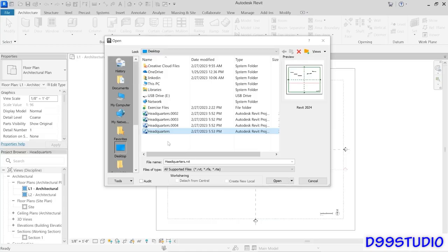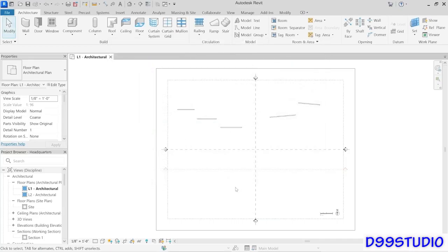So if you get in the habit of saving often, not only are you keeping your file up to date and potentially avoiding the annoying save reminder dialog, but you are also getting several backup copies that you can fall back on should something occur where you need to restore an earlier version. Now, we set it to 3. You can set it to any quantity that meets your needs, but I think 3 is adequate in most cases.